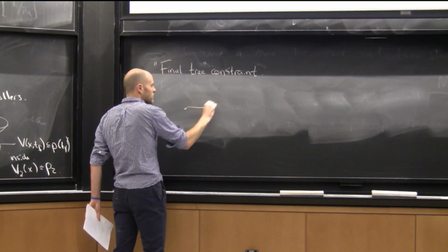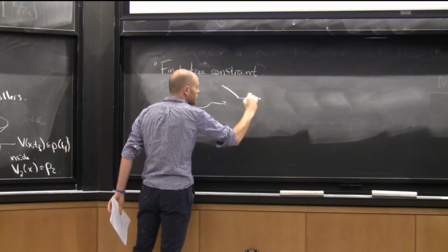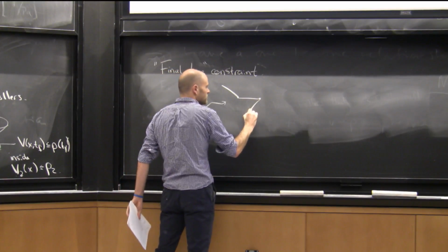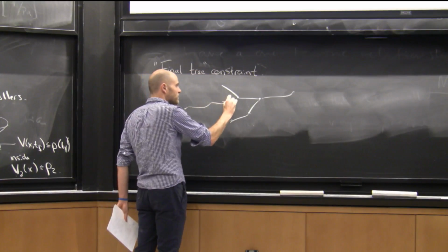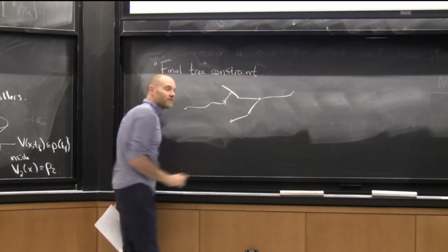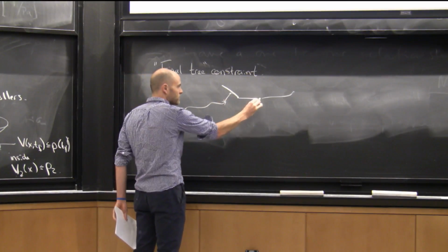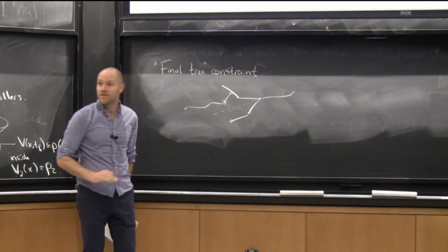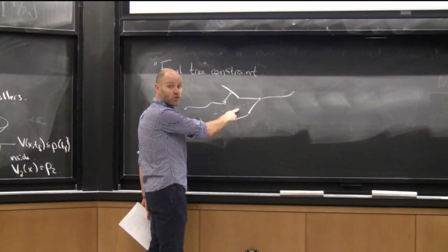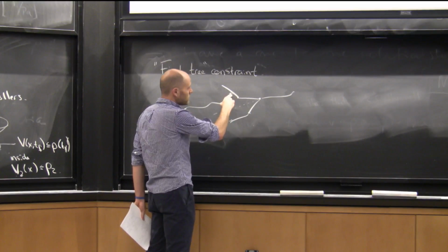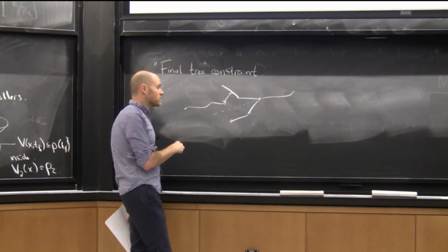So think about the problem of, I've got some trajectory optimization, and I just say that it has to land. It actually doesn't even have to land on a node of the tree, it could land in any of the continuous segments, right? So the distance between this and the tree is something you can imagine writing the distance function down, right? That distance is going to be discontinuous along the Voronoi regions. It'll be non-smooth across the Voronoi regions. So trajectory optimization could struggle with that. It'll get stuck in local minima and the like.